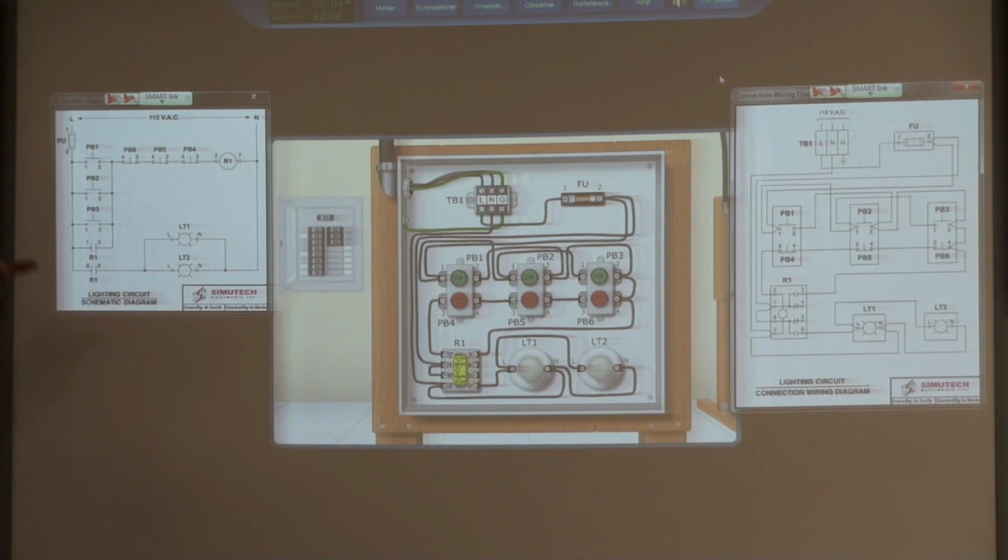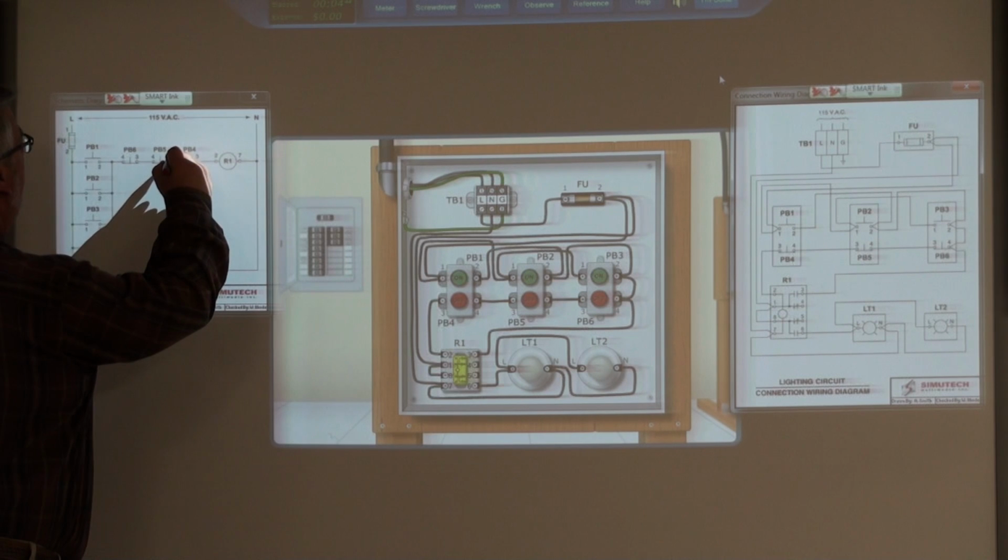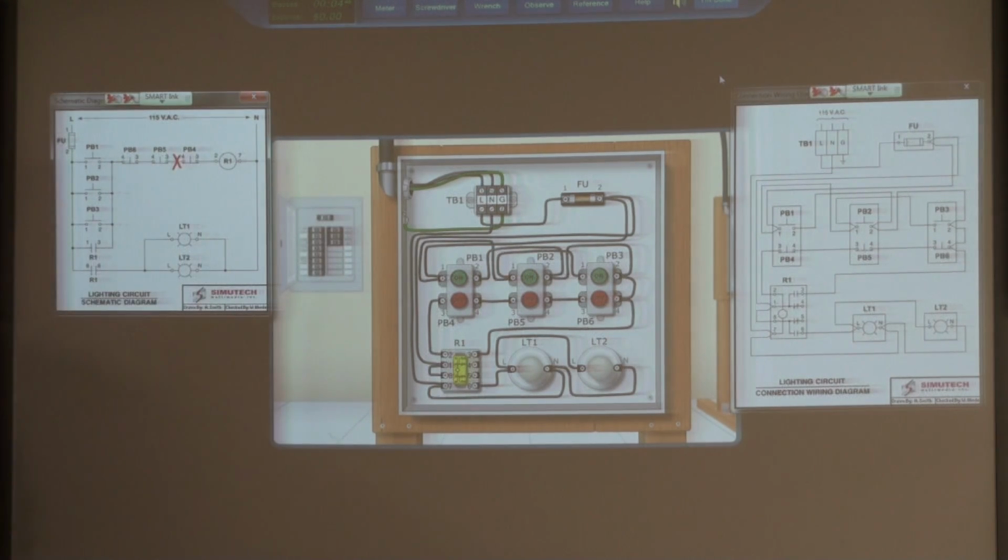The lights are on right now. The machine's operating, it vibrates, and we break that wire right there. What are going to be the symptoms of that fault? The relay will not engage. You won't be able to energize the relay. Turn it off. It won't turn off.